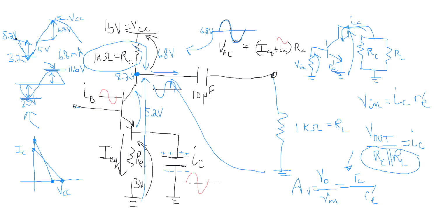If I want to raise this voltage even higher, that means I have more voltage I'm trying to push through, more current I'm trying to push through the load, and there's no source for that. So our peak is going to be limited to this new value, VC max, which is related to the mix of RC and RL. It is directly related to their ratios.